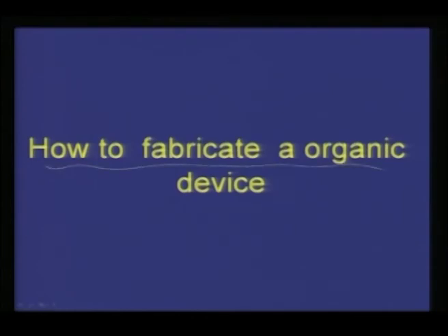Now, having discussed something about what these molecules are and how it basically works, I will spend a little time on how to fabricate an organic device. Compared to the multi layers that we discussed in the previous module on electronic materials, organic device making efforts are rather easier comparatively, but there is a stringent protocol that is followed because it has to be moisture free, although it can be handled at very low vacuum conditions. In spin electronic applications or spintronic devices, I emphasized that you need absolutely a very high vacuum, but in organic device applications you do not need very high vacuum, but a moderate vacuum of the order of 10 power minus 5 torr, that is enough.